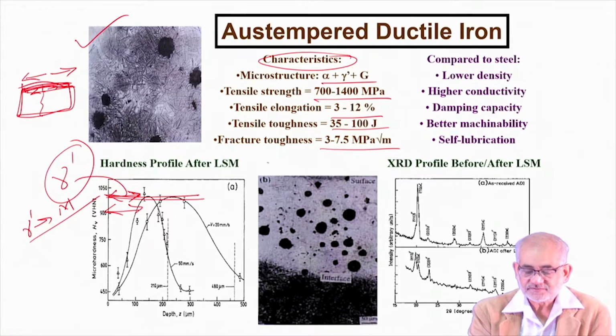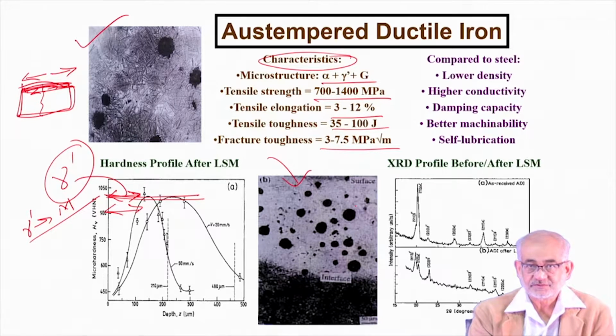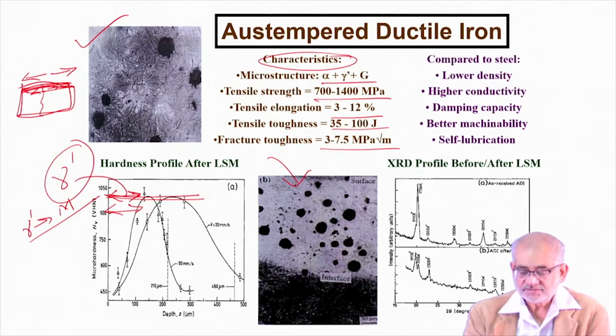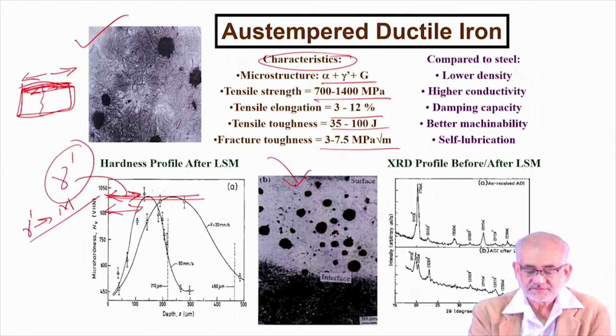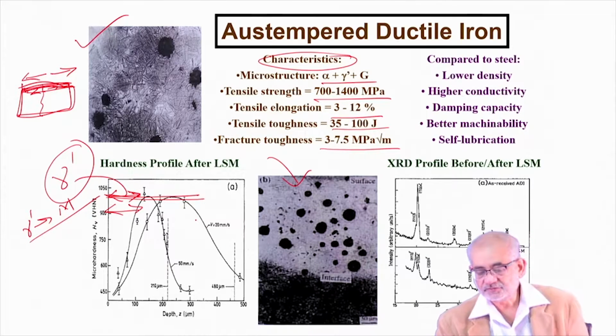And when you do surface melting, you end up getting a microstructure which will have regions of carbon-rich, semi-molten or molten regions. But the most important fact is that this is essentially a ledeburitic microstructure. And hence, because of the presence of a large amount of retained austenite, the surface hardness is low and will have a Gaussian distribution.